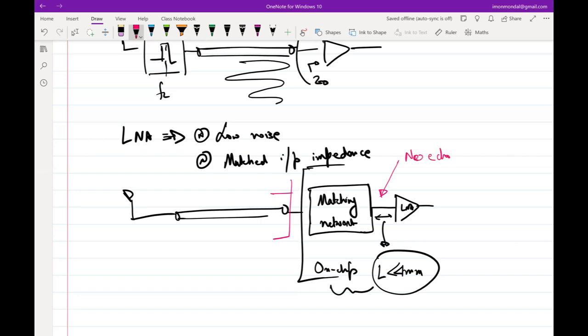So what is high frequency? That was his question, right? So what is meant by high frequency in this case? This will become a problem if lambda becomes of the order of a millimeter or so, right? Lambda of the order of a millimeter means 30 gigahertz, or even higher. They are typically called millimeter wave circuits. Because the lambda becomes of the order of a millimeter, the popular lingo is, we call it a millimeter wave circuit. In a millimeter wave circuit, you have to be conscious about the length of the transmission line, else you are going to have problems. But if you are talking about, let's say, sub 10 gigahertz, not an issue. You can basically go ahead with the lumped element approximation.